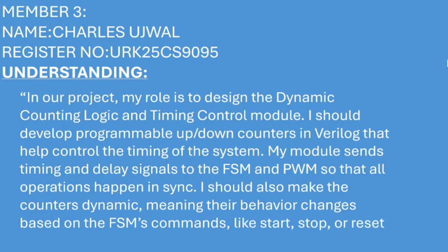Hi, I am Charles Ujjwal. In our project, my role is to design the dynamic counting logic and timing control module. I develop programmable up or down counters in Verilog that help control the timing of the system. My module sends timing and delay signals to the FSM and PWM so that all operations happen in sync. I also make the counters dynamic, meaning their behavior changes based on the FSM's commands like start, stop, or reset.